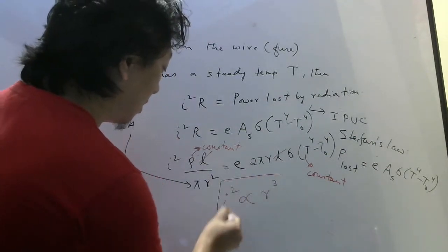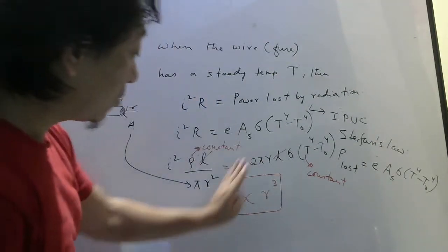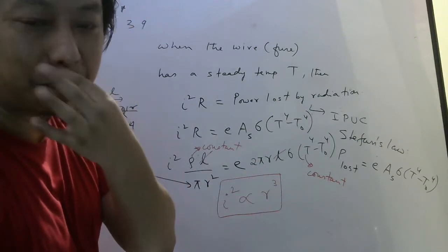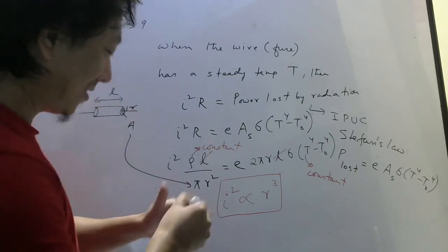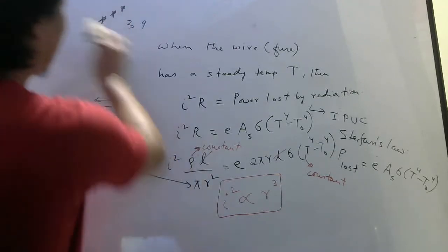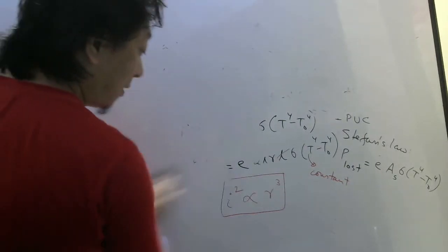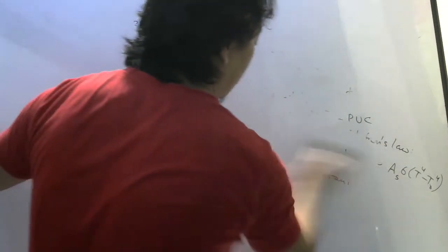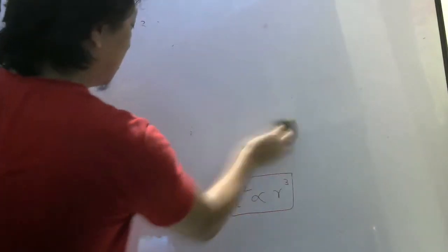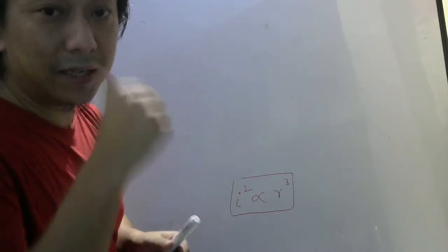So this is the formula which many textbooks use directly. I am trying to derive it. Okay. So try to remember this for your exam purpose. It is similar to Kepler's third law, right? Similar to that, but obviously there is nothing gravitational going on here. So remember this I is the maximum current at which the wire will be about to melt. So this is also called the limiting current. So when you buy a fuse, that limiting current will be mentioned.